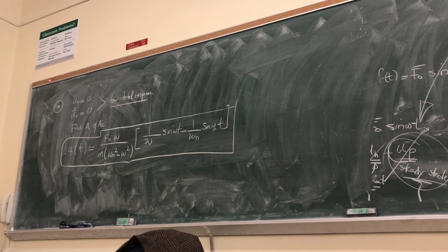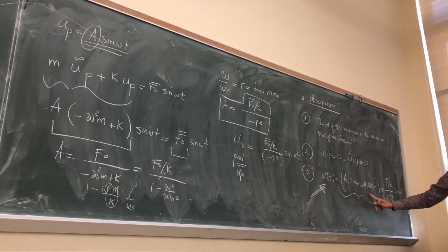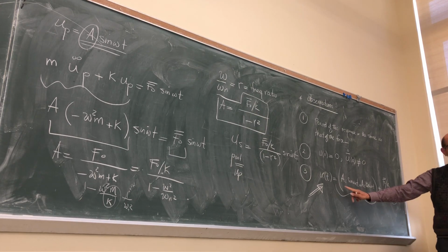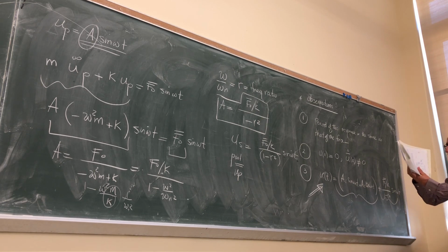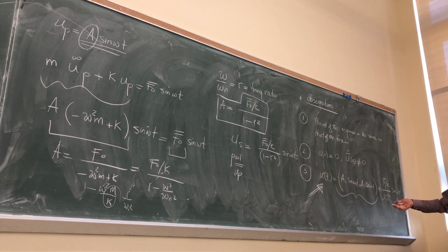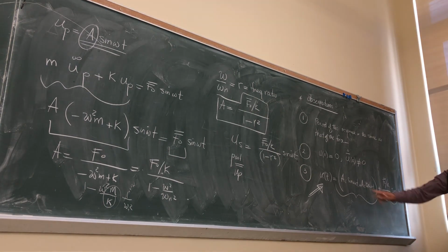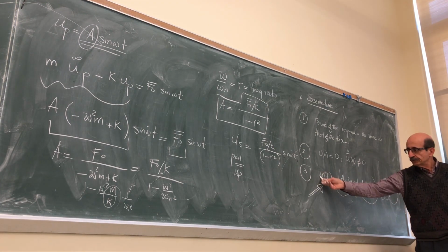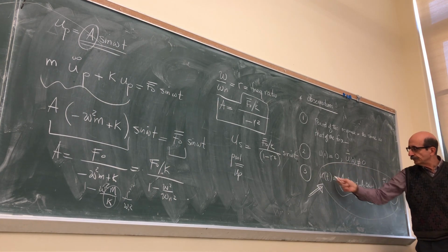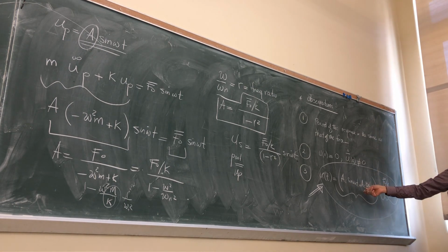No, we are assuming now, this is the total response, and for this total response we want to evaluate the two unknowns. The assumption we made is that this response has started with zero initial velocity. In other words, you have zero initial velocity, you induce a forcing function, and let's find out what the total response is. In general, this is the total response, so in order to find these two unknowns, you have the two initial conditions, and substitute in here to find them.